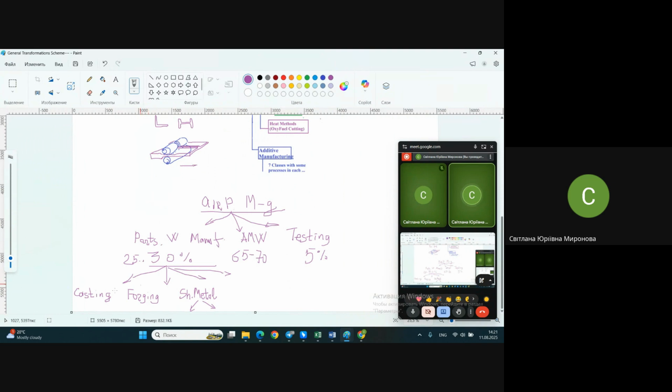The same goes for subdividing the casting and forging shops. Why? Casting is rather similar to forging; the difference is that casting is in liquid state and closed die forging in solid state. Equipment is different. Machinery is quite different, as necessary for accomplishing one or another process. And as equipment is different, we divide into shops like this: casting processes and forging processes. Open die forging and closed die forging we consider similar processes because they use the same equipment. However different they are in their physical principles, in what happens inside, nevertheless they are usually in the same shops because they use the same equipment.